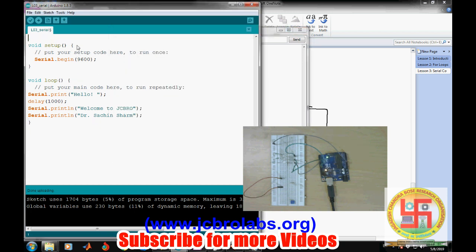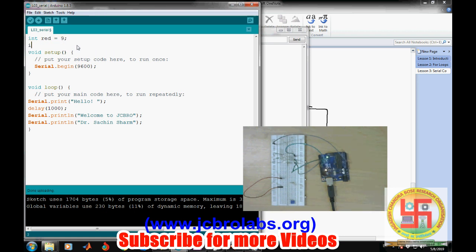We write int red equals 8, and int blue equals 9: blue is connected to pin 9 and red is connected to pin 8.